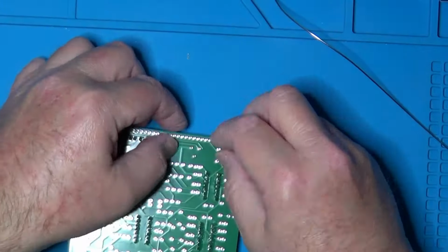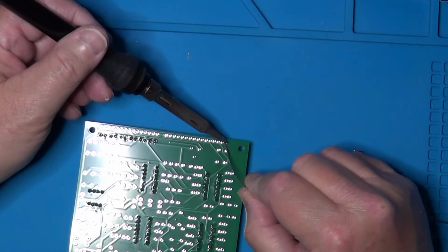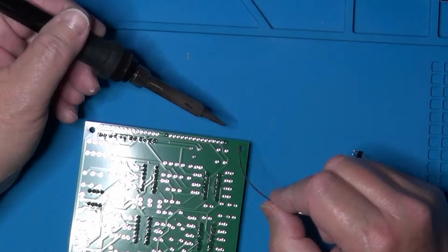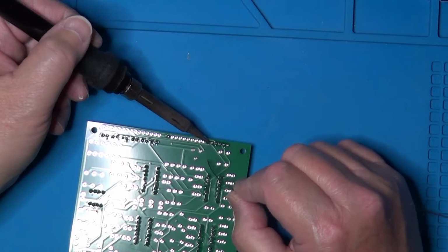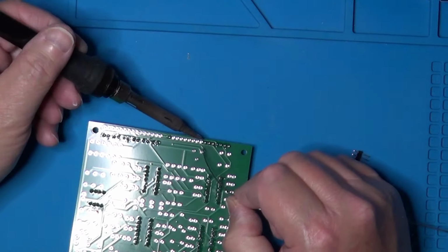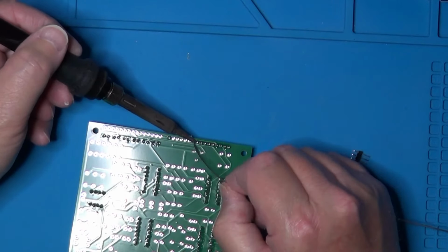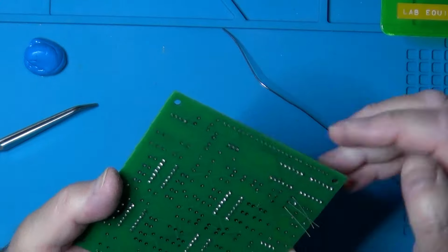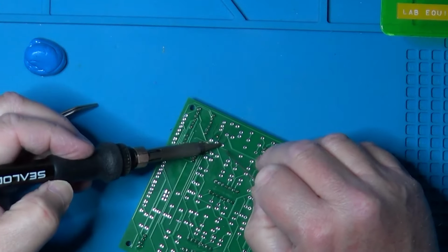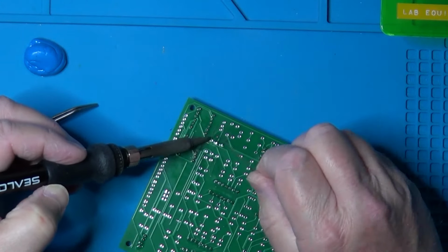The PCB is also made in such a way that all the headers toward the Arduino are on the same edge of the board, while all the headers that connect to the components on the front panel are on the opposite edge. The board is packed with very little space around, so the leads of all the components need to be bent very close to the body of the components themselves.